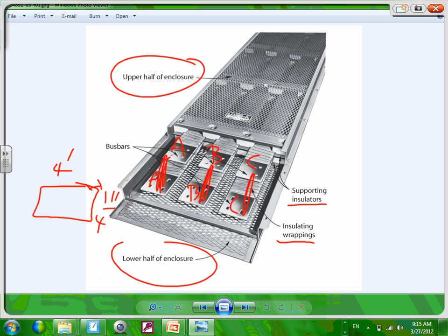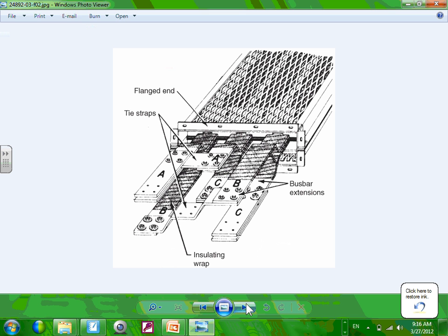And Chris, everybody knows why this is ventilated, right? Why do you think it has holes in it? It allows these buses to ventilate. If you allow them to ventilate, to conduct the heat away from them, they can carry this amount of amps. If you completely enclose them, like if this is to be outside, rated for wet location, I can't use it. It has to be weatherproof. So you completely enclose it, then you have to derate. You get into a whole lot of different derating. So that's your busways.